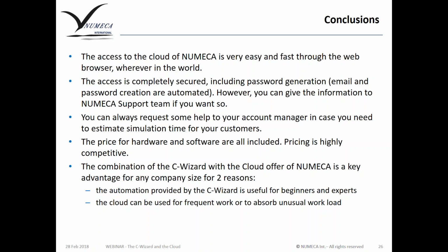And if you don't have enough confidence, or you want to do something extra that C Wizard did not foresee, there is, of course, no problem. You can always change the settings afterwards, either by changing them manually inside the interface or by adding a script on top of it. So the C Wizard is not at all a black box. It's very important to remember that. We don't want to force you to use the settings that the C Wizard has created. It's just a default setup, which is very, very good, I would say, and also totally standard for all the CFD simulations that we are proposing as applications.